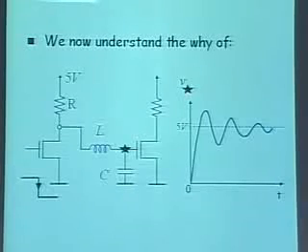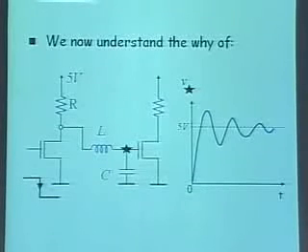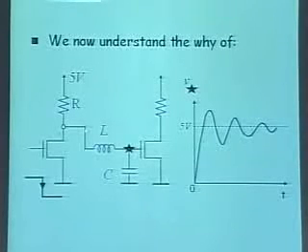After a long time, this capacitor looks like an open circuit, and the inductor, an ideal inductor, looks like a complete short circuit for DC. And so in the long term, it is as if this guy is a short, this guy is an open, so 5 volts simply appears here. And this is the transient behavior when we just switch the first transistor off.